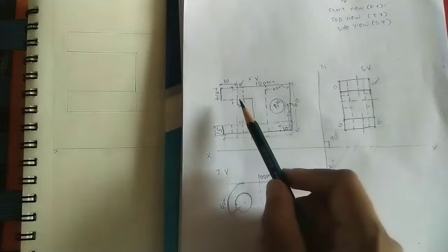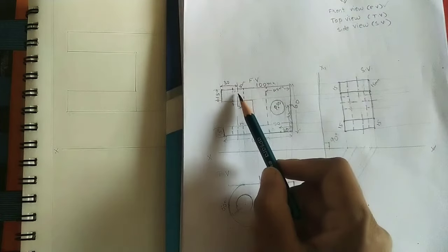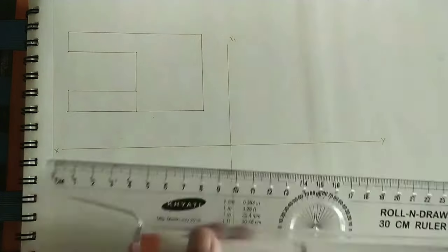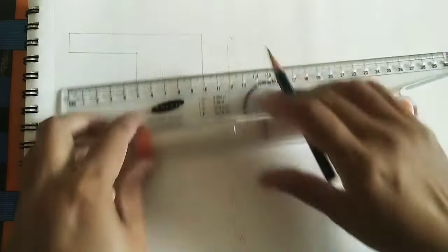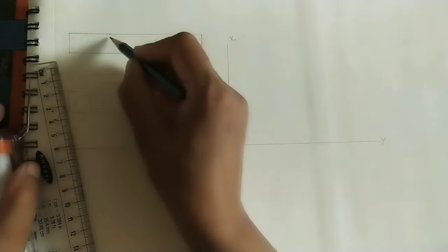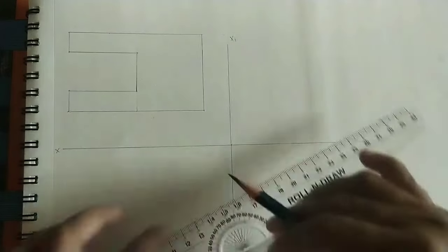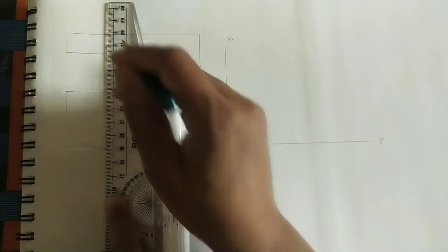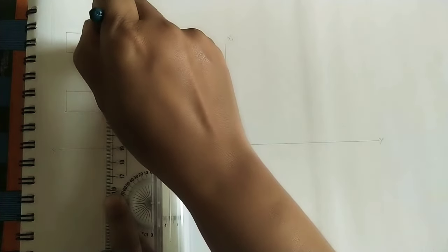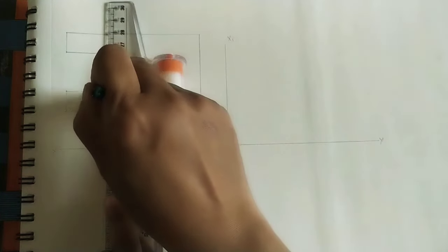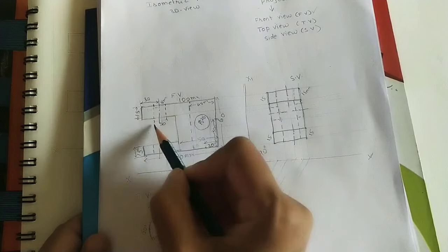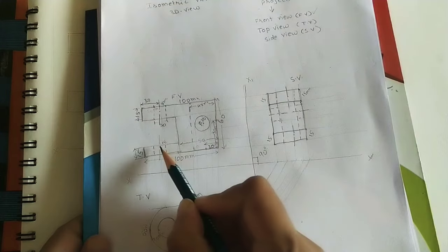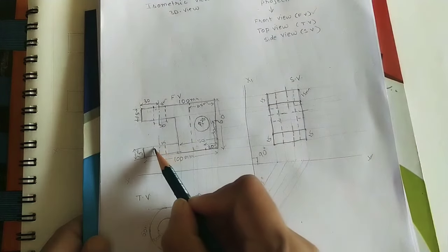Now after getting it, here do the axis line. It is 30 mm. Take 30 mm. So at 30 mm do the axis line here and here. Axis line means two big lines with a dot, like this. After getting the axis line, here do the lines. The gap is 30 mm. Okay, radius is 15 mm. This side 15 mm, this side 15 mm.